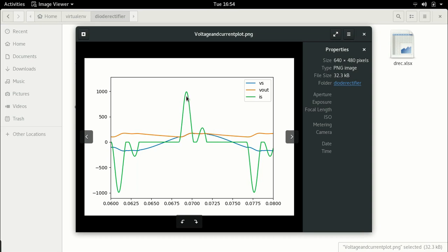That's when the output voltage drops. The reason it drops is because we have a large resistance at its output. This large resistance is discharging the output capacitor. And when the diode rectifier starts conducting, it starts drawing a current. Here these two are kind of superimposed, but you see this point, this is the negative term.